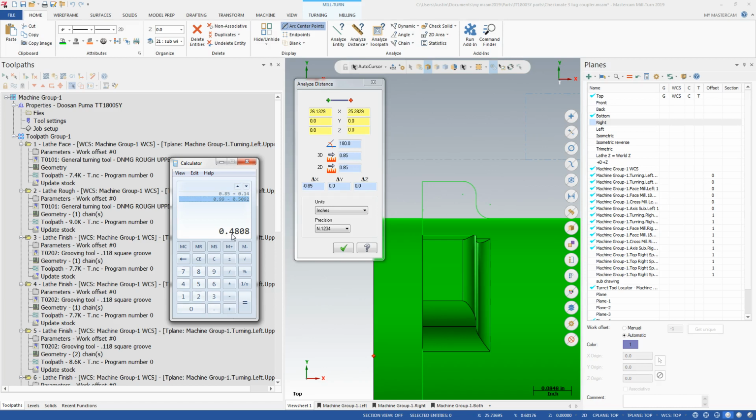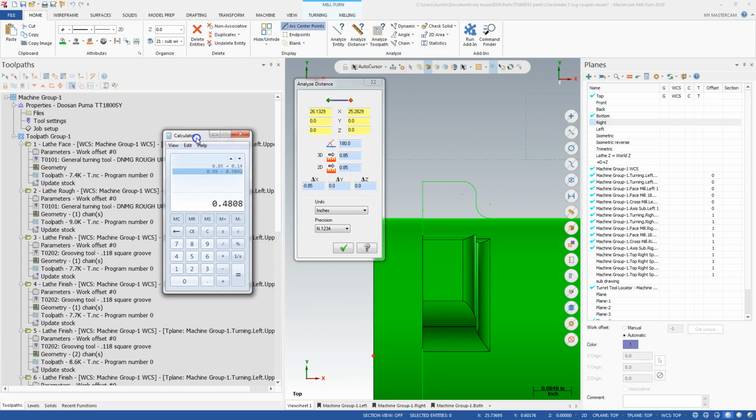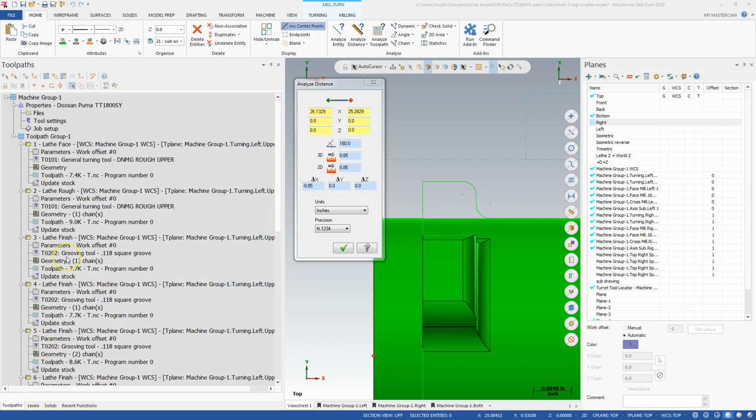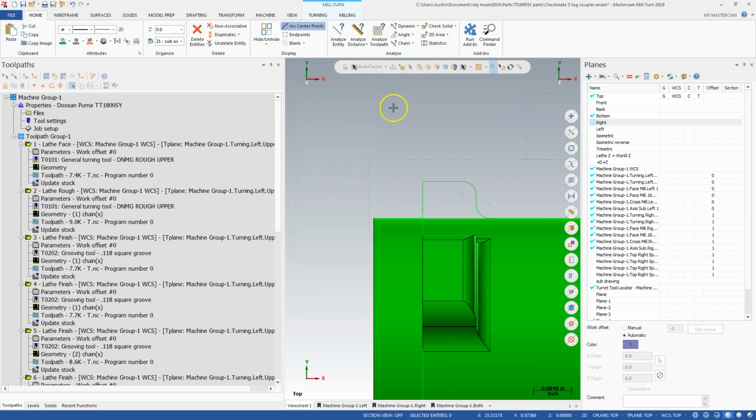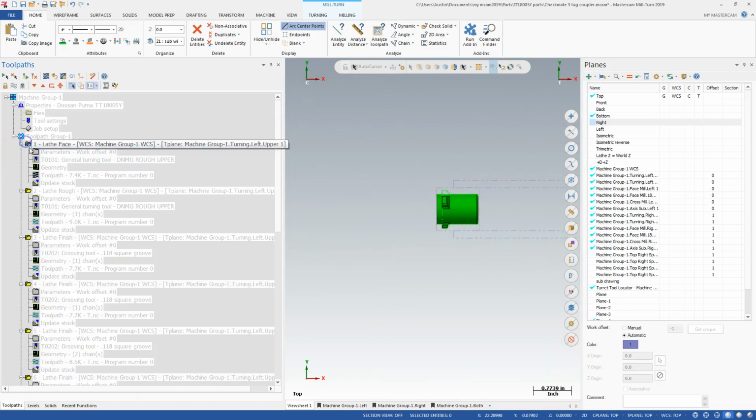And that'd be an example for if the finish I was gonna get off my parting tool would be good enough. And then if we don't get the finish we want off of parting, we can always change this value in the control of the machine and leave ourselves some face stock and maybe take a tool like our ID CCMT for the bore and come up the face and face the part. So I have my numbers that'll be useful for later. We're going to grab the operations we're going to post.